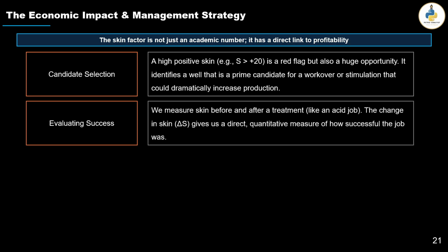Evaluating the success of any treatment: if we know the skin factor before the treatment, either it is acid or hydraulic fracturing or a chemical treatment or anything, and we measure the skin after this treatment, we can quantitatively measure how successful the job was.